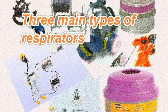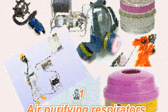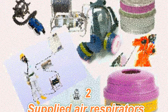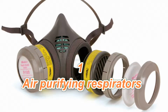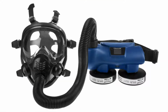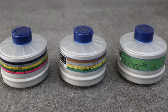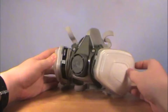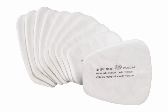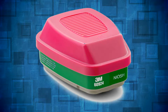In reference to protection from inhalable chemicals, respirators can be divided into three main groups: air purifying respirators, supplied air respirators, and atmospheric air supply respirators. Air purifying respirators come in different types of fittings and shapes, but the basic feature is that they all use filters, and these filters have different quality and protection ratings. The user can change filters of different types: dust filters, oil filters, organic chemical filters, and gas filters.